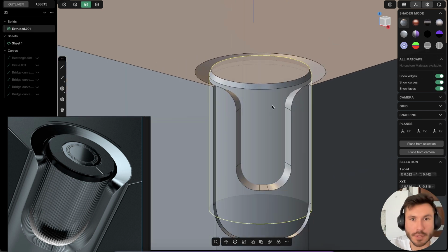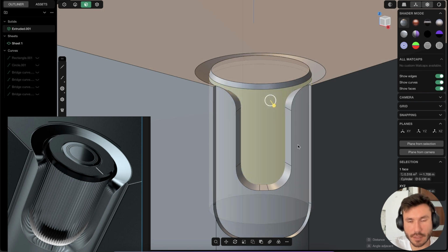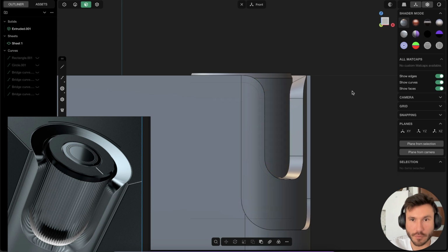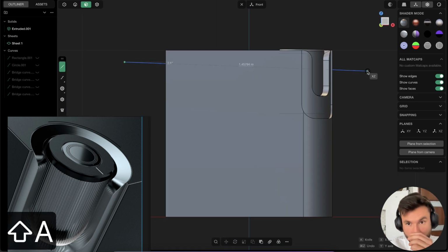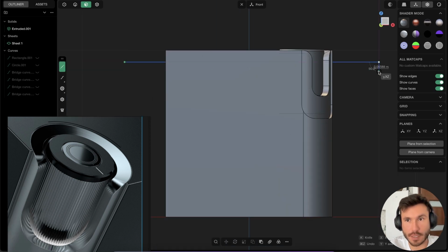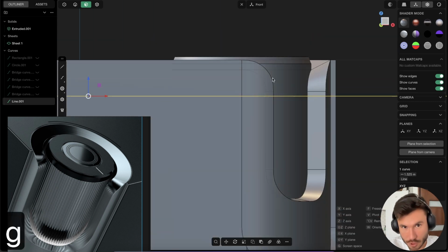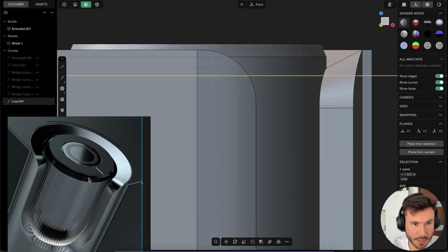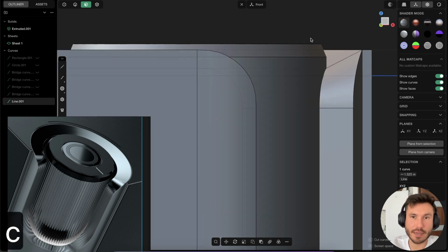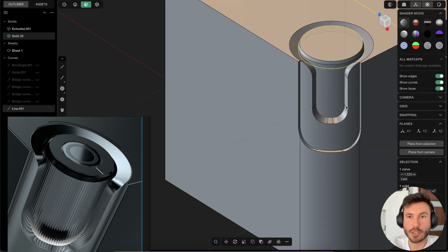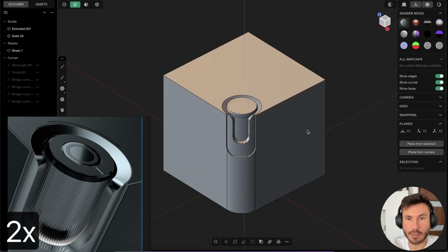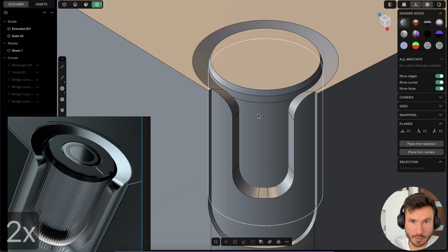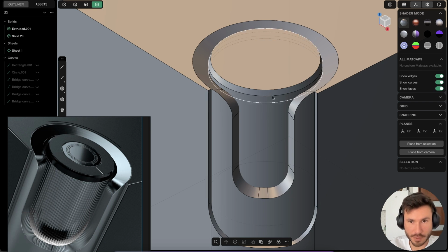And let's make the ribs super easy. I just want to cut this whole object in 2. So I will go to the front view, just create one massive long line, so like that, straight. And now with G and G again, I just want here a little bit of a distance. Now press C and cut into your cylinder. So you can delete the line, and in object mode, you see you now have these 2 separate pieces.